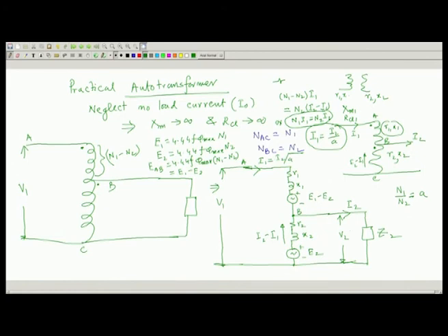Acha. Now, this voltage is V 2 and this voltage is V 1 applied voltage. Terminal voltage, induced voltage, they are not now same, there will be a little drop here. But this tells me that the voltage across, so called across AB portion of the winding, this must be V 1 minus V 2, it has to be this voltage minus this voltage, V 1 minus V 2, with this side plus this side minus.